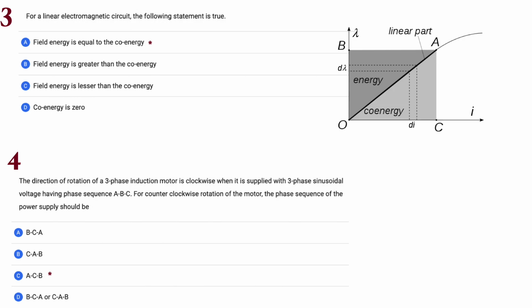So what becomes the phase sequence? It can't be ABC or BCA or anything like that. There should be an exchange. So we see that BCA is the same as ABC. If you continue to read it becomes ABC, ABC, ABC. Next is again ABC, because it is CAB, CAB, CABC. So you can see that it's the same. The third one, that is C, happens to be ACB. Now there is an exchange. So ACB is right. We don't need to go further. So these are all very general, as also basic kind of things.